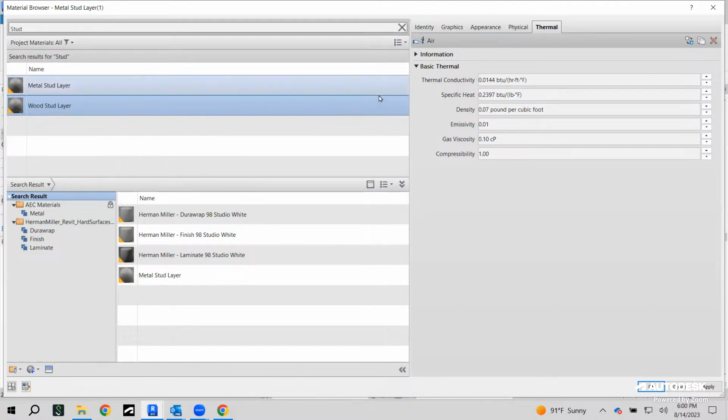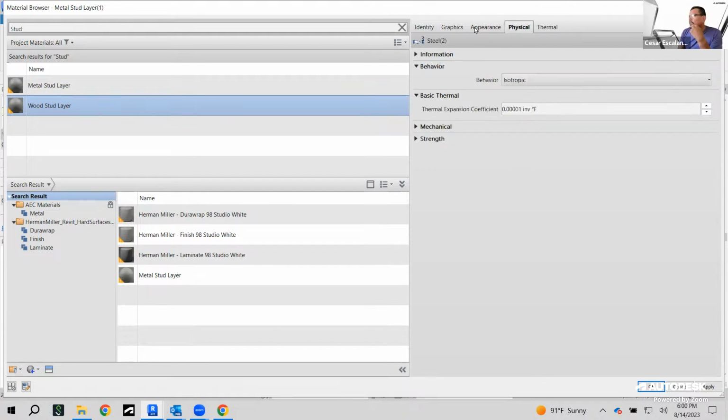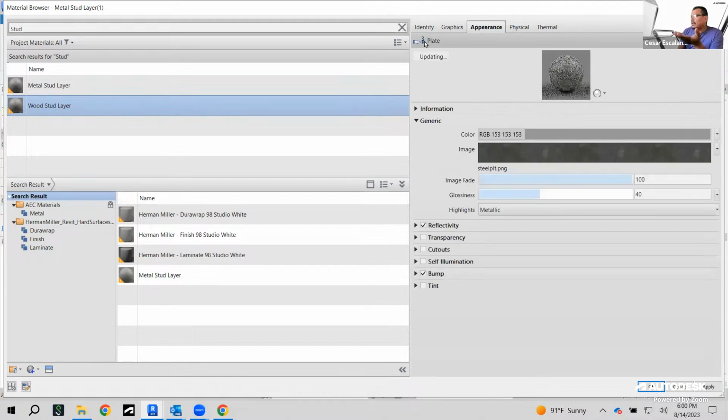I have a question as well. So when you do that step, the top right of your screen where you have the paper that's overlapping, you still want to duplicate with the selection you just made to duplicate all the assets so you can change them individually because they're still tied to everything else in the project, correct? Yeah. And if you notice, I used to have the icon with the little 2. Now it's changed to 3 because the plate is now in use by 3 materials, including the wood stud layer.